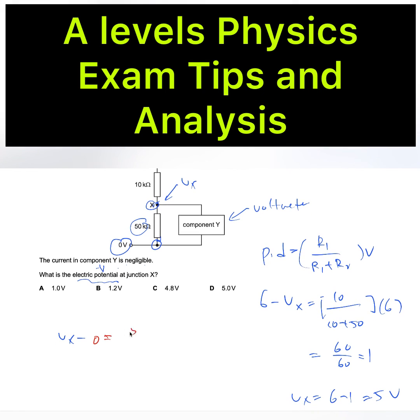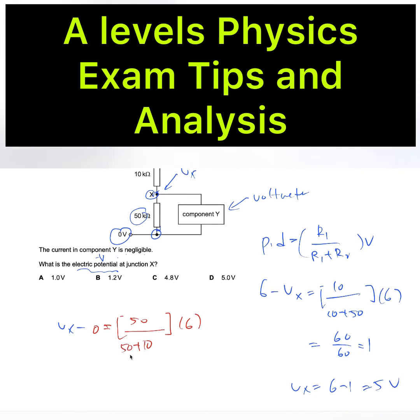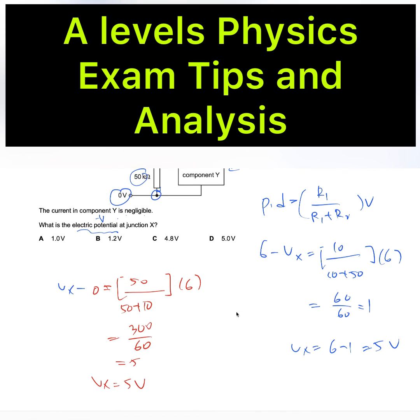This is 50 divided by the total resistance, 50 plus 10, applying the potential divider rule, and then you multiply by the power supply, which is 6. From here we get the same thing: 300 over 60, which is 5. Then Vs will also be 5 volt. The answer will still be D.